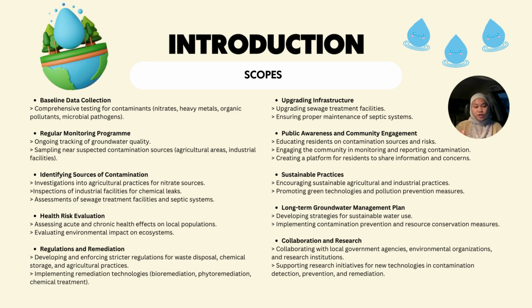Next, we move to the scope. The first one is the baseline data collection, which is comprehensive testing for contaminants like nitrates, heavy metals, organic pollutants, and microbial pathogens. And the next one is the regular monitoring program. It is ongoing tracking of groundwater quality and sampling near suspected contamination sources, like agricultural areas and industrial